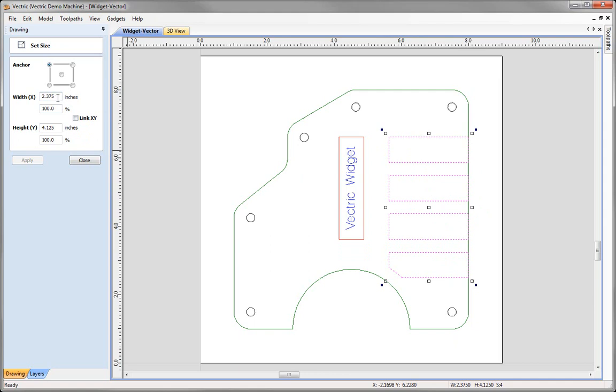And in this case I'm using a quarter-inch tool to pocket these out, so I need to make sure they extend past the edge by the radius of the tool. So I need to add the radius of the tool onto here. I could either manually calculate that, or I could enter that as a calculation into the software directly. So there I've got my original size, and what I could say is plus 0.125, which is the radius of the tool, remember, not the diameter but the radius, and then hit equals on the keyboard to calculate my value.